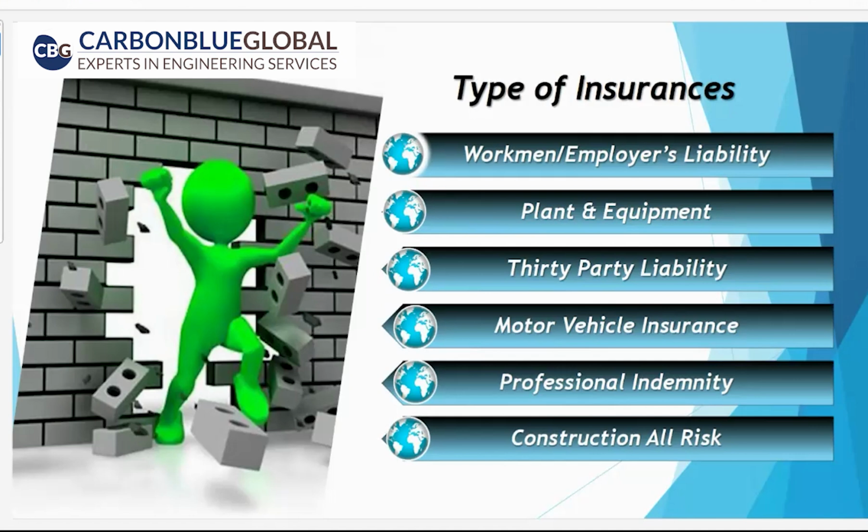The next one is professional indemnity insurance. Professional indemnity insurance usually gives coverage to a party who provides professional services, like design services, design consultants, or cost consultants. This gives coverage for the liabilities that may arise from the error or negligence of the professional services being carried out by these professional companies. Besides that, contractors who have any design responsibility within the construction contract will also be required to procure professional indemnity insurance. Usually it will remain valid till the insured services have been completed, with an extended reporting period of 5 to 10 years.